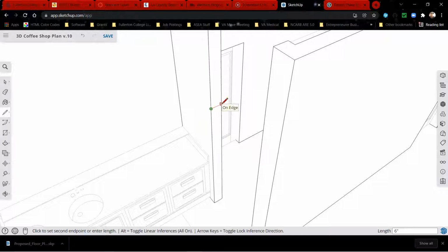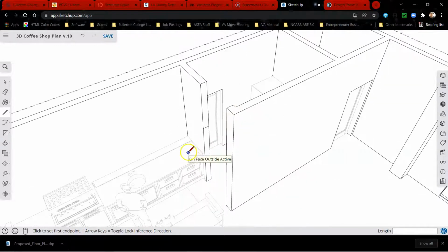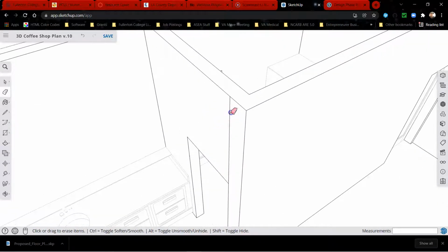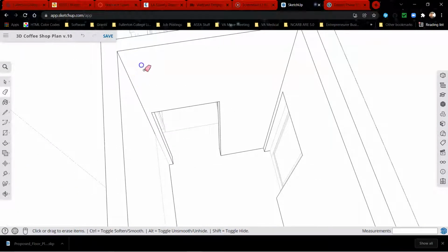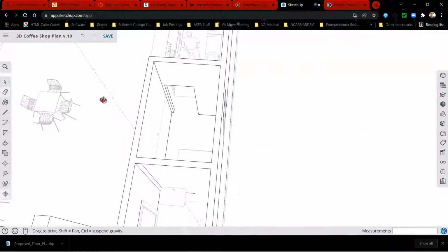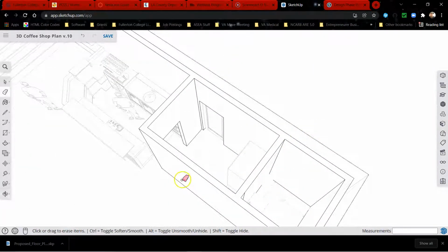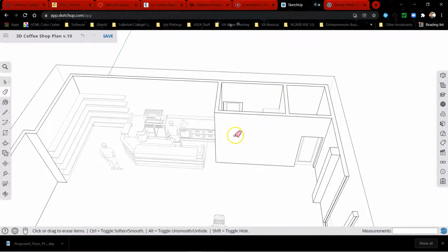And so I'm going to switch to the line command, which is the letter L, and draw that line. Push pull and snap to this corner. I love snapping to the corners because I know it's going to change into that green little circle. And it's super easy to identify. I really don't have to mess with it.